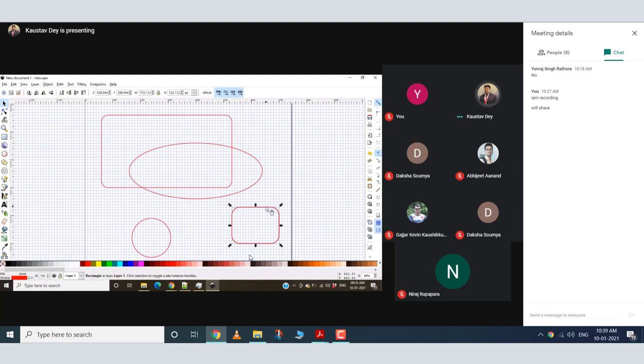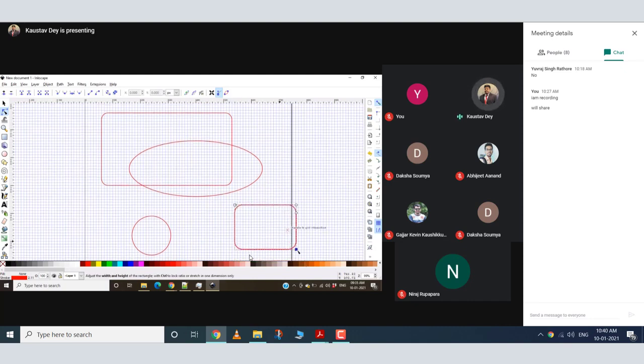And then, we are still not done with the curved vertices. Once you go to edit path by nodes, you see these three different nodes. These two nodes are very obvious. To enlarge the figure, drag these nodes. This was the start node and this was the end node. You drag one vertex, and the opposite vertex position does not change. That's how it enlarges.